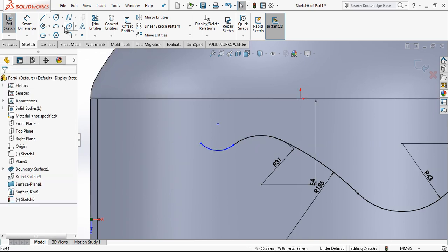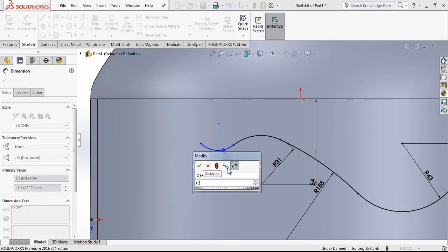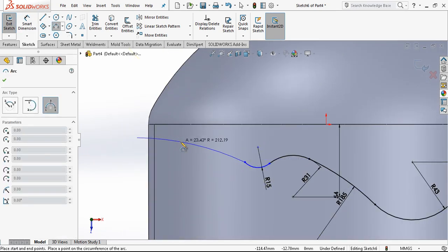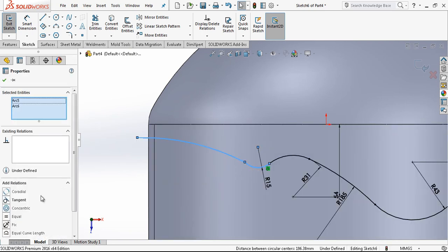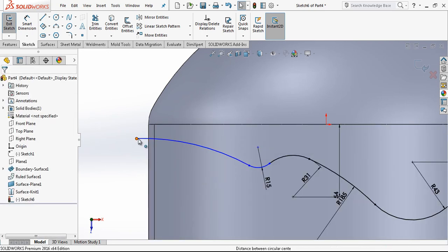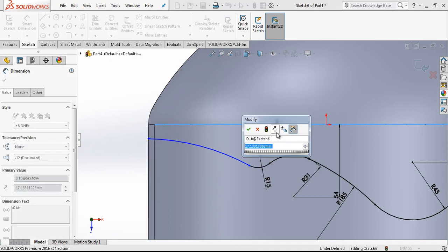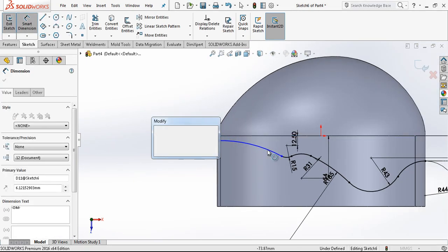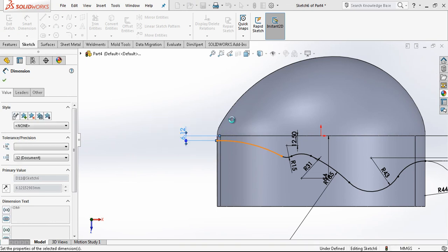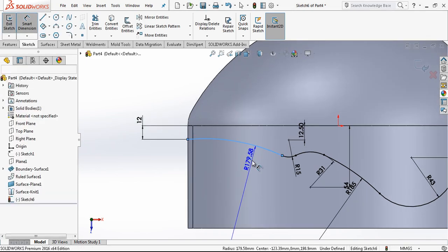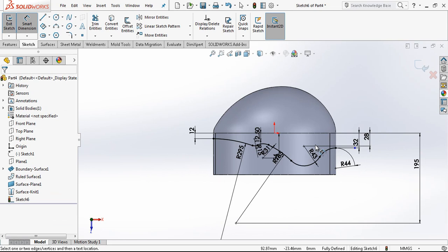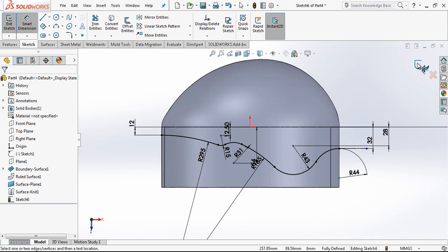I'm not using, as I told before, probably in the other videos, so many splines, because splines are not proper when you are making a revision on your sketch and you are not all the time sure about the curvature and the condition of your sketch. For that reason I prefer working with lines and arcs, by giving exact values.